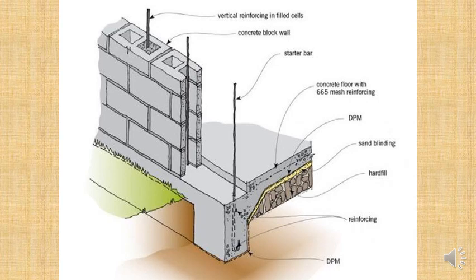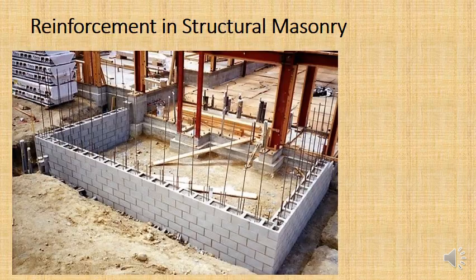So you set them in with concrete, and now if that building is in an earthquake, it's going to shake, but the steel bars are going to take the tensile and shear loads. So the masonry wall takes the compressive load and the bars take the shear and tensile loads. So this is very common.